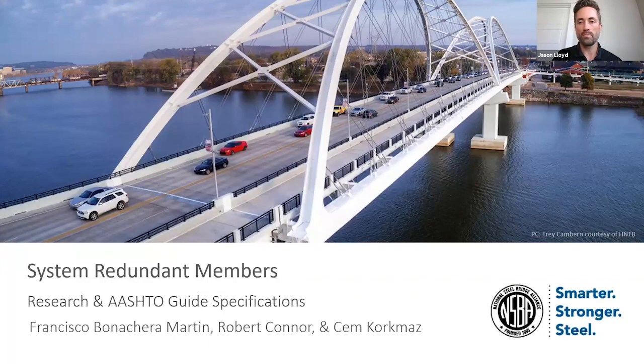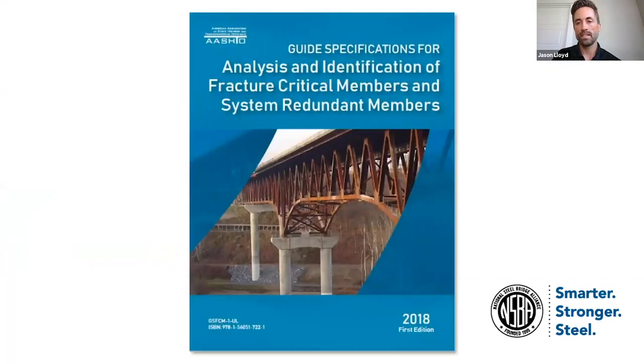So let's dig a little deeper into the development of the guide spec for SRMs first. The essence of this guide specification is a standardized Federal Highway approved method for the analysis of systems for system level redundancy. It codifies the level of refinement of the analysis, the demands or the load combinations for a target reliability, and establishes acceptable performance criteria for a bridge in the faulted condition.